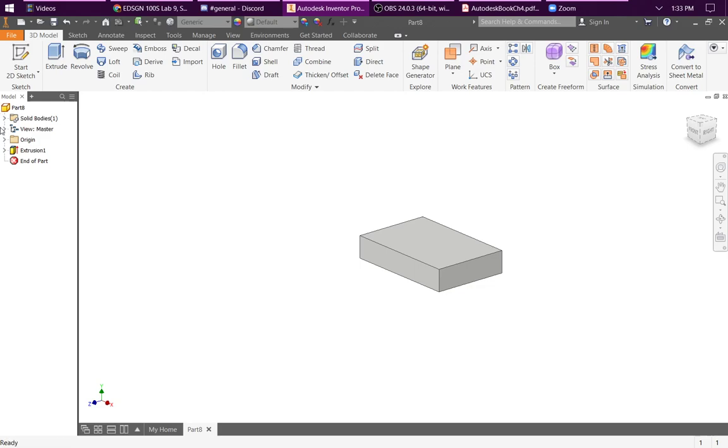And the next thing we're going to do is add another solid feature. So we'll have another 2D sketch, and as before, you can either use the planes that you have from the origin, or you can use surfaces of the part that you already have modeled. And we want to make the sketch on the bottom surface, which you can't see right now.